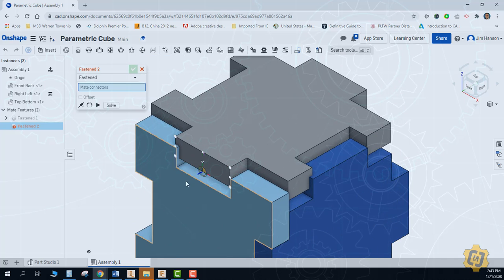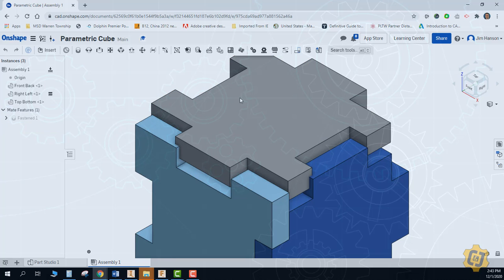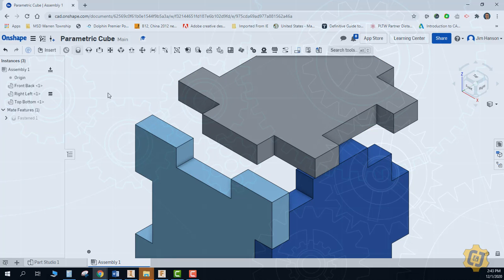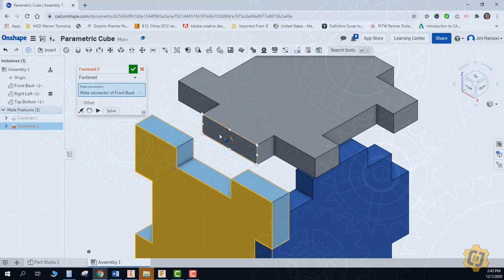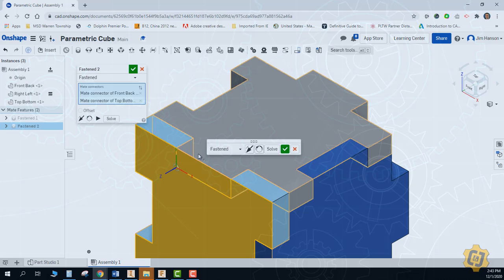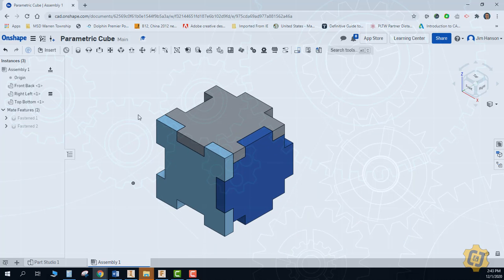Let's do the same thing with the gray. So wiggle my mouse around, pick a point, and unfortunately that one may be a little bit difficult to get. So I'm going to exit out of it, pull it up and away from it, so I can try that again. So wiggle it around, do a little circle, this point, a little circle, and that point. Great. So now I can just drop in my other 3 pieces. I'm just going to highlight them and do a Control-C, Control-V for copy and paste, or you could insert them again.